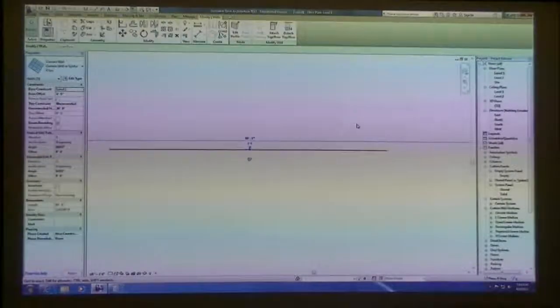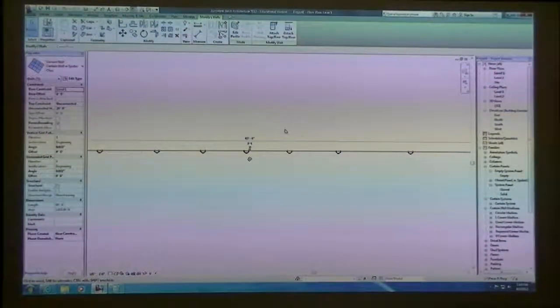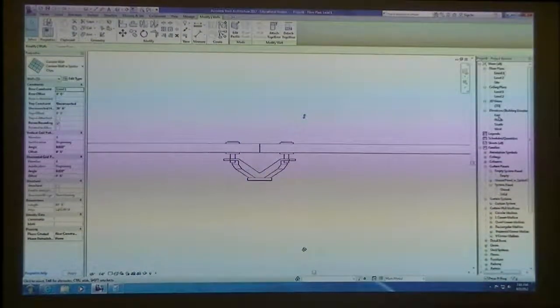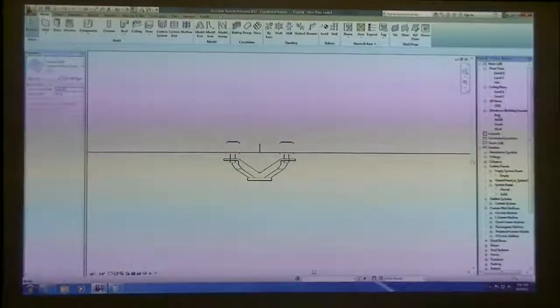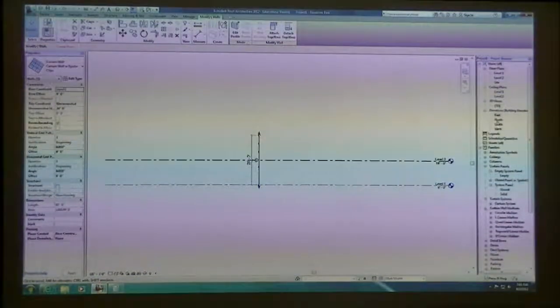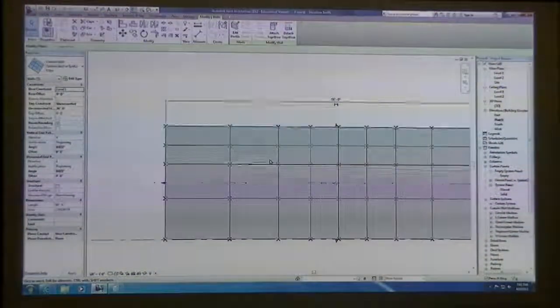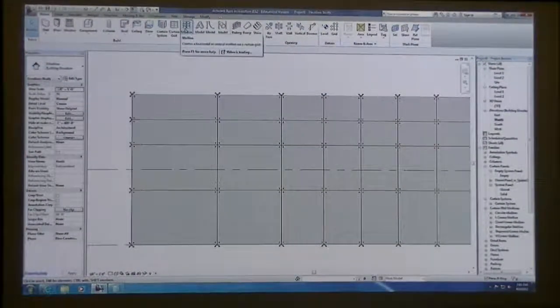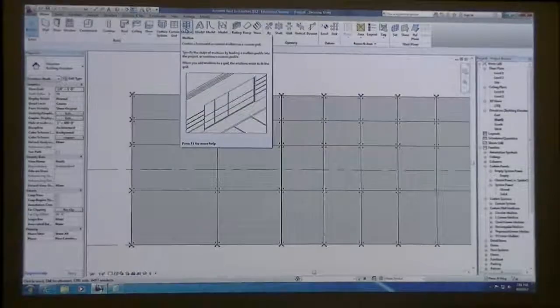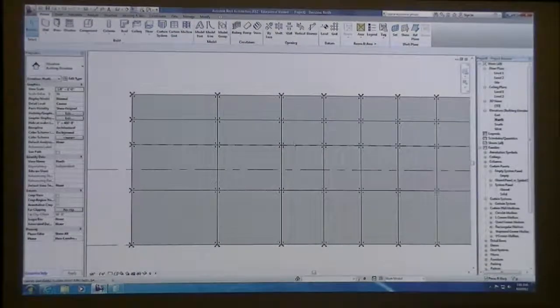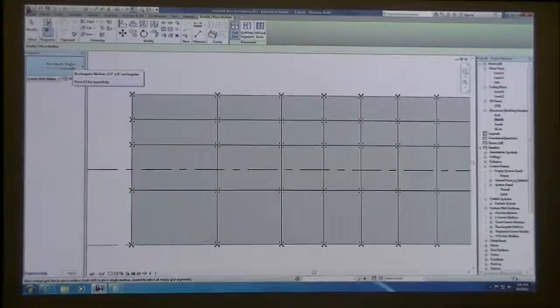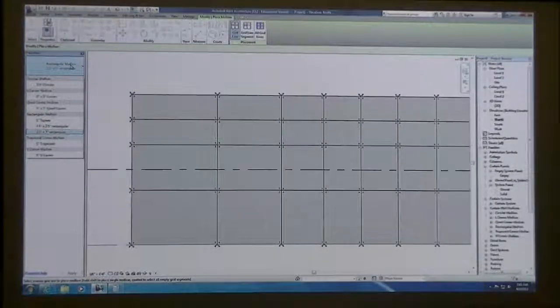So I'm going to just go into a floor plan view, and we can zoom in. This would really need to be in an elevation, sorry. One that's perfectly looking at the glass. And if you remember, in the last class, we went over how to start to place mullions. So if you're in the elevation view or 3D, you can click on mullion. And then over to the left, there are other properties and different mullions that we can place.